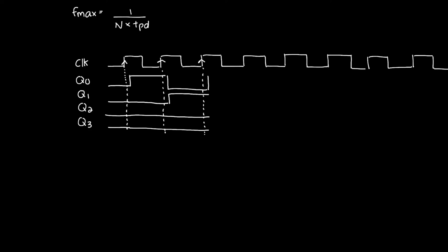Now, how do I know this? Because over here, if I look at Q3 as the most significant bit, this is Q2, this is Q1, and this is Q0, well, they're all low. In other words, they're all logic 0. Over here, I have 0, 0, 0, 1. And I know I'm counting up. It's mod 9. So what do I have here? 0, 0, 1, 0, 0, 0, 1, 1. In other words, these stay 0.